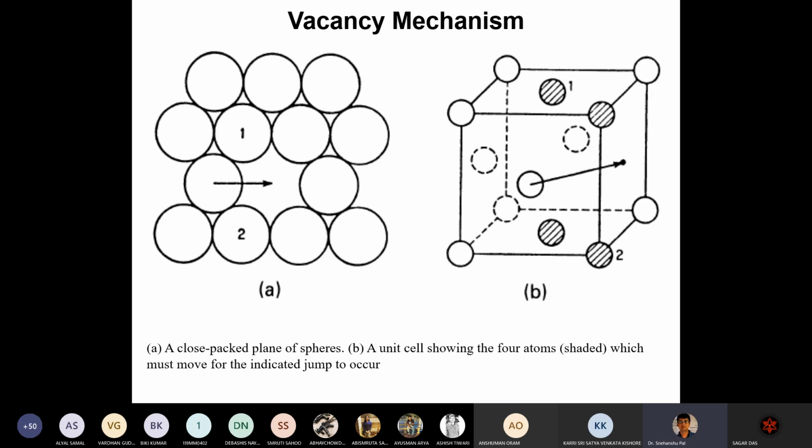Now in the figure, you can check the nature of the constriction which inhibits motion of an adjacent atom into a vacancy in an FCC lattice. If the undistorted lattice is taken to consist of close-packed spheres of diameter d, the equilibrium distance between the restraining atoms will be 0.73 d.